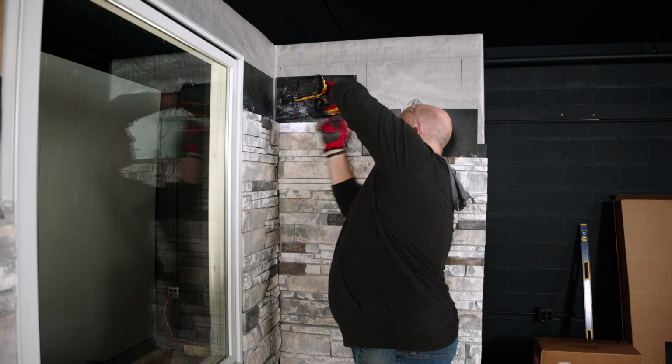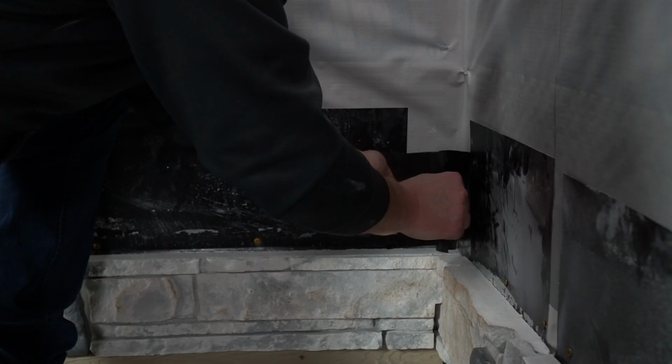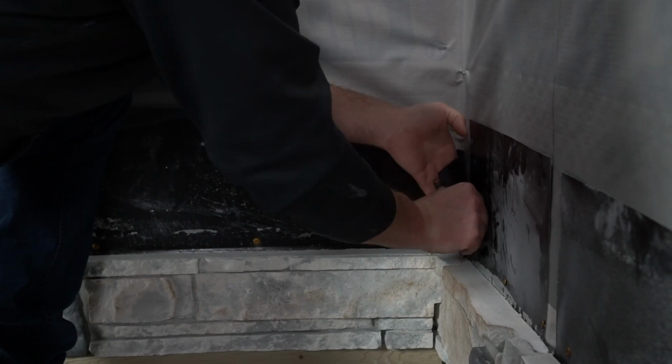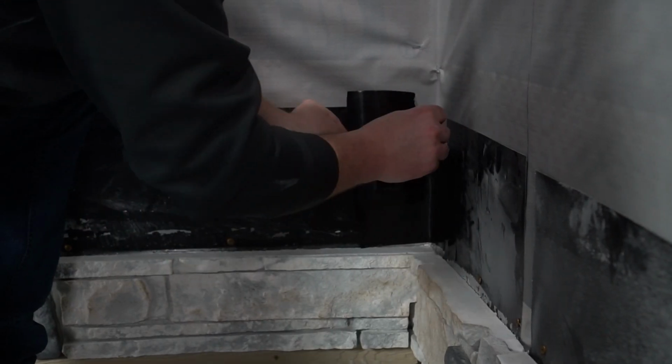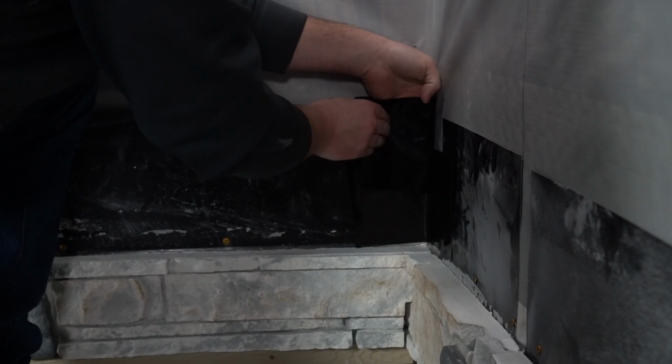You will notice that the flashing for the panels do not overlap as the flat panels do. In this application, cut and adhere a piece of self-adhered flashing, SAF, over the integrated flashing, covering the exposed corner. Do not screw through the SAF, as this could allow water to get behind the assembly.